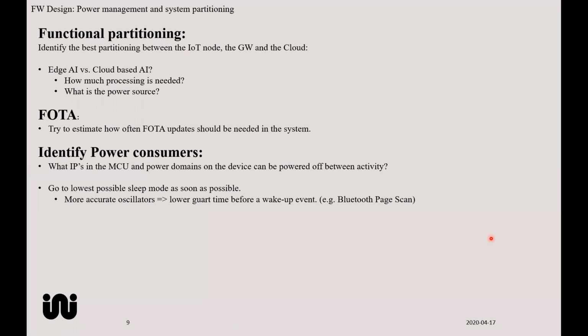If you need to wake up way in advance to make sure that you're absolutely powered and running when the paging time comes, of course that will consume more power. And that is the case when you have a less accurate clock. You can't rely on the frequency exactly, so you need to have some kind of guard time before, so you make sure that you're alive when the paging occurs. The same goes for Wi-Fi. So a more accurate clock will actually make a huge difference over time.